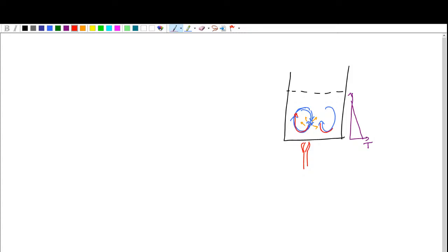And similarly, in this case, warm water rises up and cold water comes down. And because of that, that carries along that spot of dye with it, and because of that, it will mix faster than it would under just simply molecular diffusion. So this is transferred due to the fluid motion rather than the molecular motion. It is transferred due to the fluid average velocity.